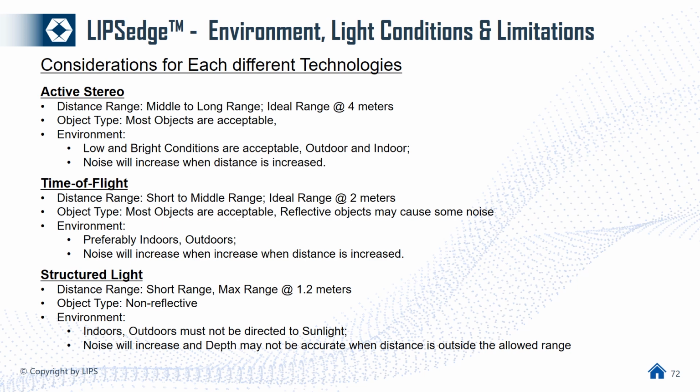Regarding time of flight, the distance range is short to middle range, within an ideal range of 2 meters. For object type, most objects are acceptable, though reflective objects may cause some noise. And for the environment, preferably indoors, not outdoors. Noise will increase when distance is increased.